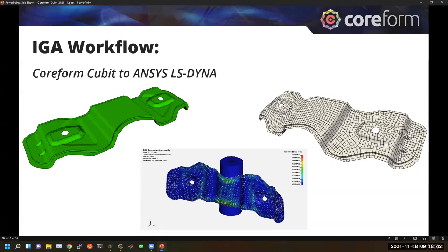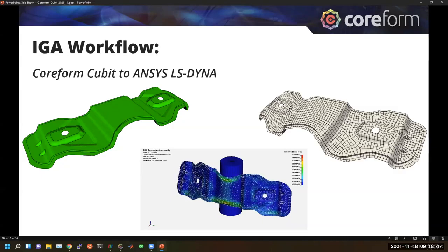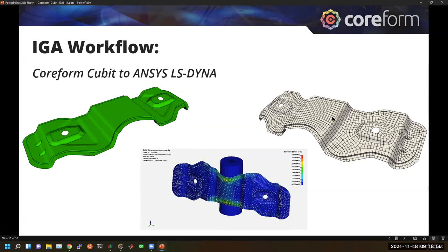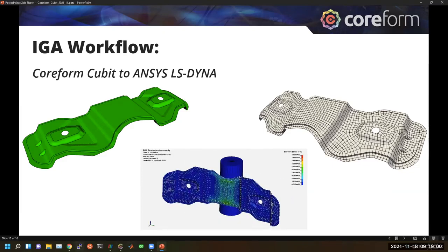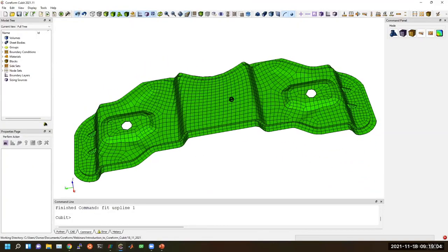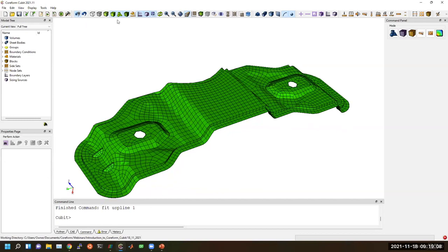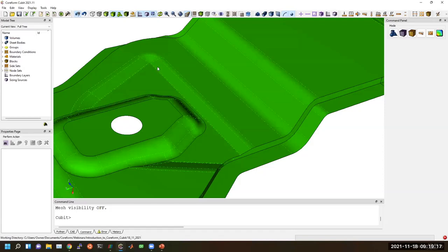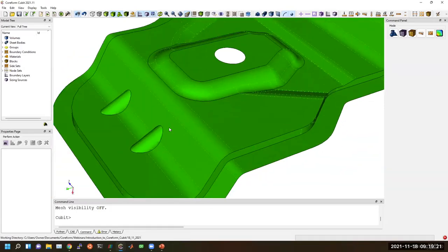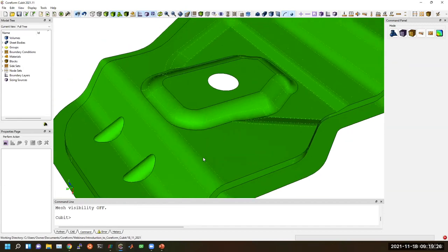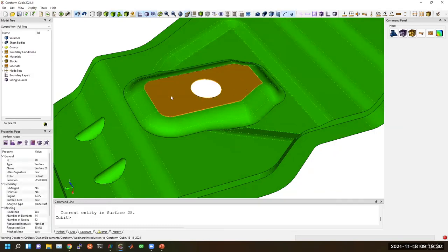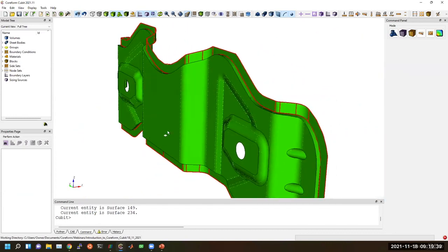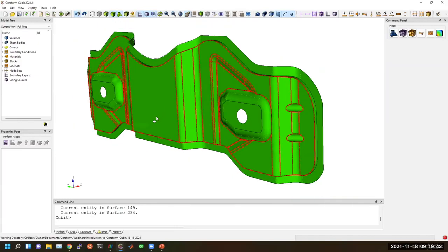I also talked about being able to build IGA workflows for ANSYS LS-DYNA, again, using U-splines. And so I'll show a demo of this as well. As you can see, we can take a model geometry, build a U-spline, and then actually run it today in ANSYS LS-DYNA. In this case, what I've done is I've taken a model geometry and used a traditional workflow prep to apply compositing of all of these unnecessary CAD surfaces, or interfaces, that are really just artifacts of the CAD modeling process. I've segregated out my model so that I have a region to apply a boundary condition onto. So if I wanted to apply boundary conditions on these surfaces, I could. And then we build a quadratic basis, and then we throw this at a cylinder in ANSYS LS-DYNA.